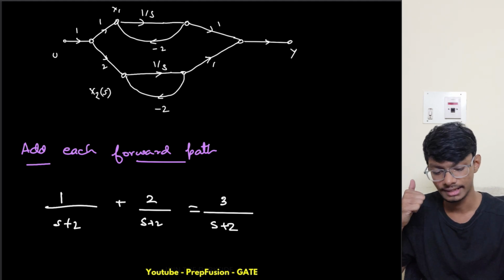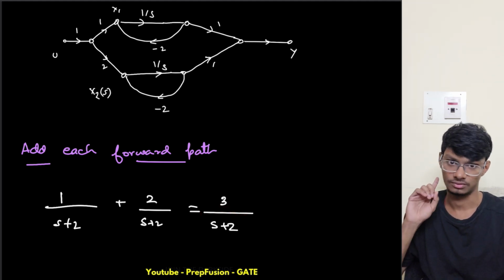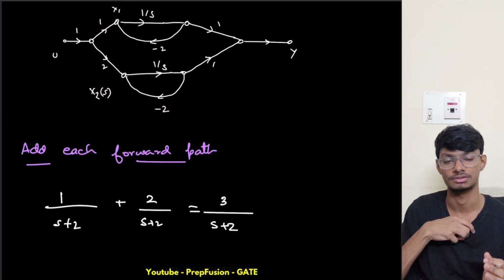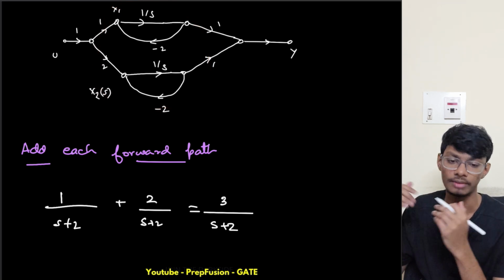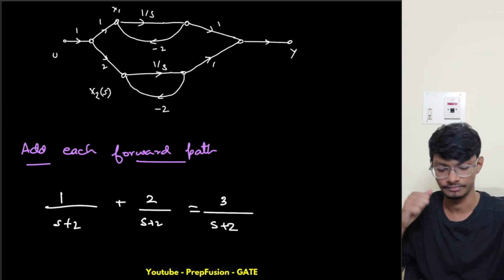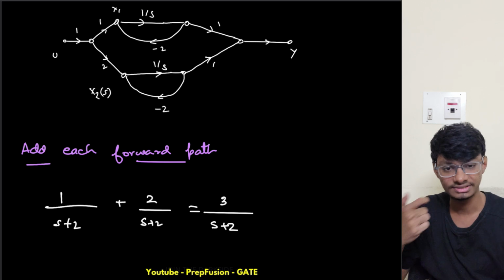From there you will not understand that there is a pole zero cancellation, but here you can understand that the order of the system is 1, and I'm using 2 integrators for representing this system. So that's why I'm not using a minimal set. That's why my system won't be controllable. This is basically the reason why it isn't controllable.